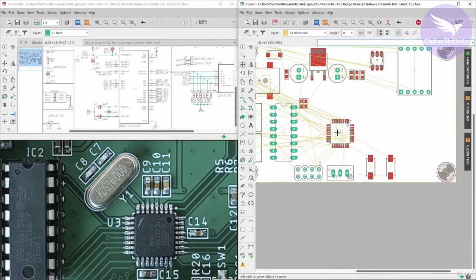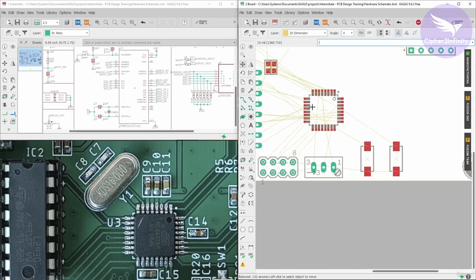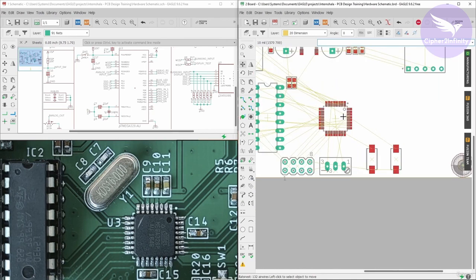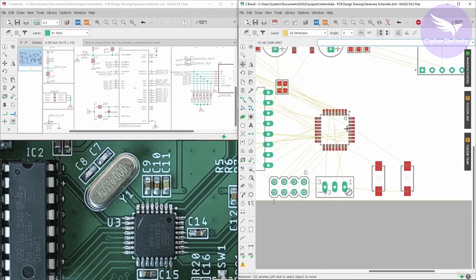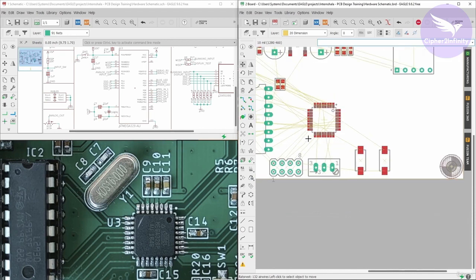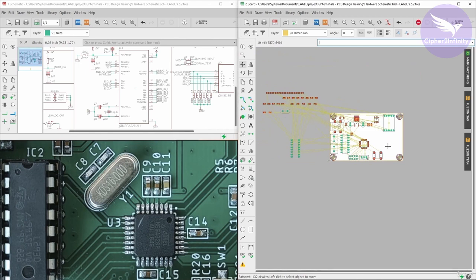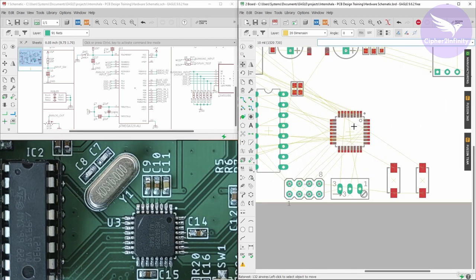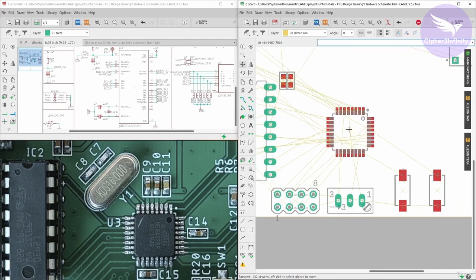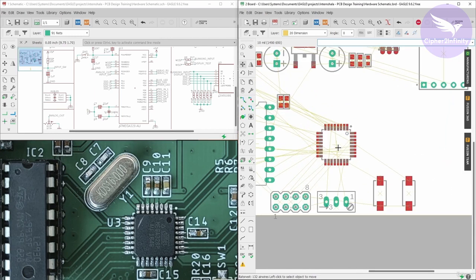And how you will take that decision, I will tell you. First of all, I will click on rat nest. You have to make sure where most of the connections are going, and accordingly choose the orientation of the controller. You can see here the potentiometer connection is here. Then the switch connections, you will not see directly at this moment because a lot of components of this switch are placed here. But you have to make sure what will be the suitable position for this controller, which will make the connections to its peripherals direct. So we have to reduce the complexity of the layout.